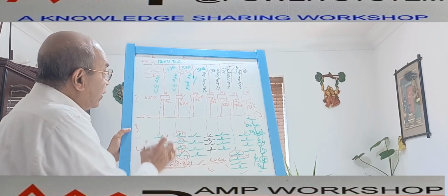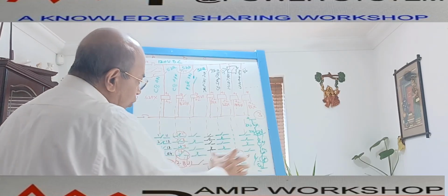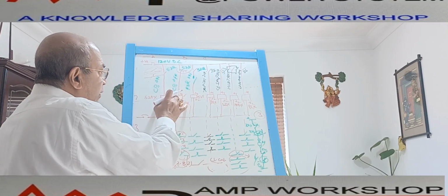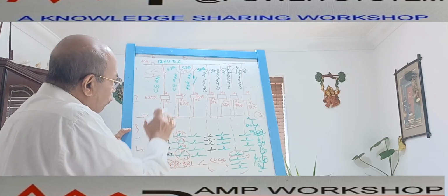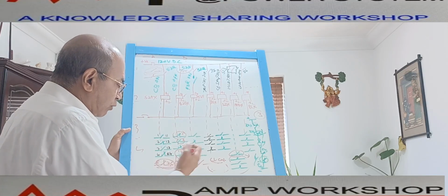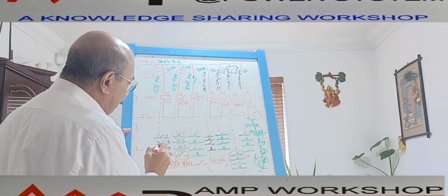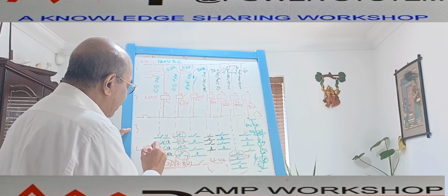Now these are the various auxiliary contacts, and this drawing is normally made this way. We make the coil with the sensing signal shown on top, and at the bottom, for each coil, how many contacts are available and where those contacts are going. If suppose I am not using a contact anywhere and it remains idle, we write down spare, meaning it is not used.